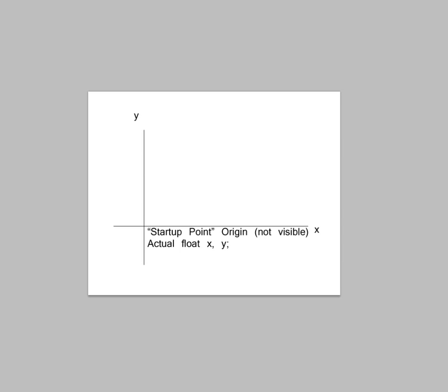First, when you draw your building or your property lines, you want them to be orthogonal to the internal coordinate system, which of course is the same as being orthogonal to the project coordinate system, since project north is always positive y internally. Computers can't exactly represent oddball numbers, and by oddball I mean non-terminating fractions like 1/3 or irrational numbers like pi. When you draw a building rotated with respect to the internal coordinate system, you end up with a lot of these oddball numbers as the input coordinates of walls.